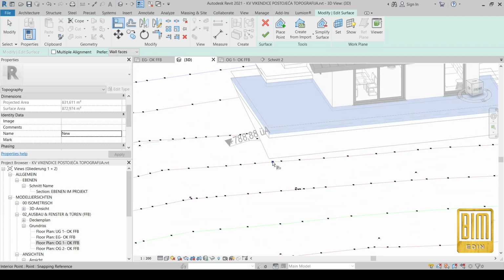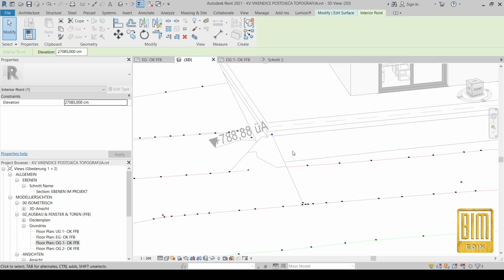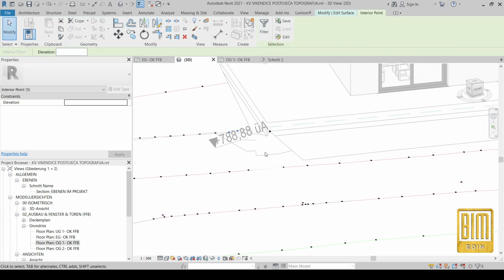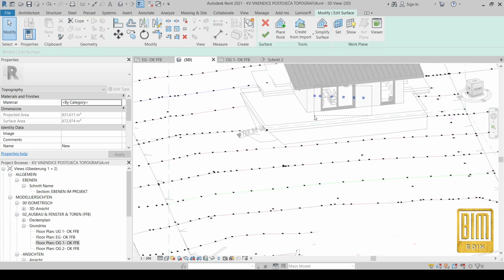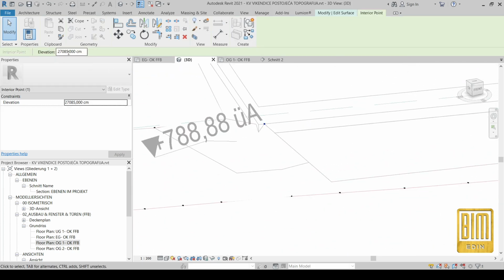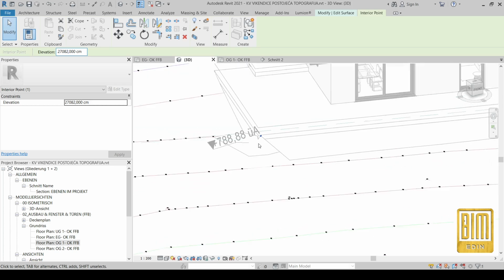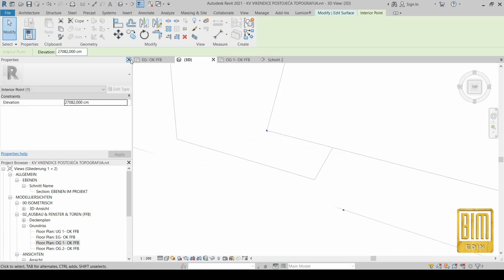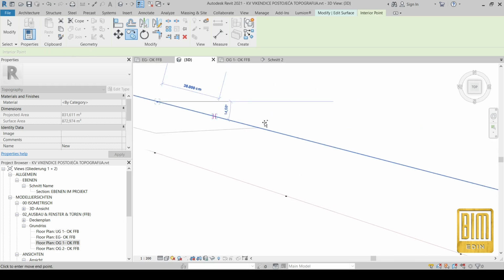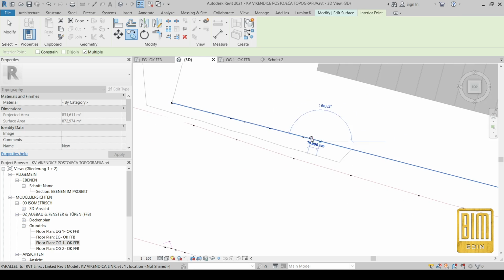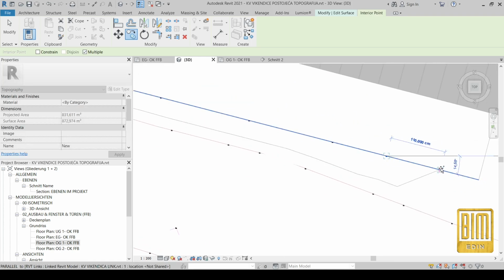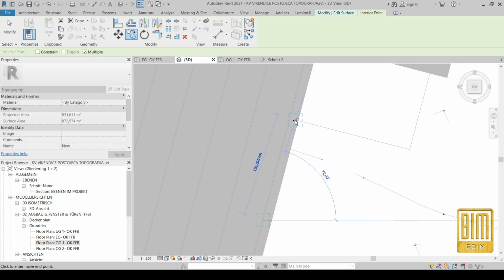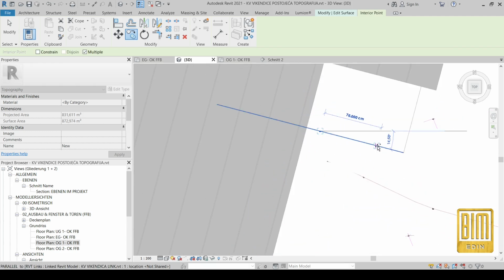And now, using align tool, I will align only this one point to the terrace view. All right. Now these points I will delete. I will change here only for 3 centimeters lower on this point here, and I will place it on the corner, and I will copy it using multiply copying to this line of the terrace here. Now as much points as you can place, this will be better.